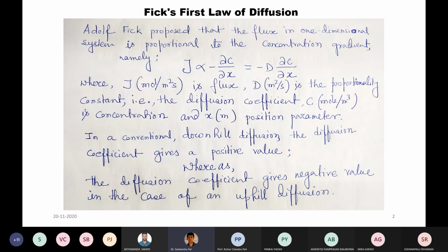And if you want to look at it more critically, it can be applied directly only if there is no change in concentration profile with respect to variation in time. That is almost impossible to find in most practical examples in the metallurgical industry sector, in metallurgical phenomena. So this is a real problem in applying Fick's first law to all kinds of metallurgical phenomena, because mainly things are unsteady, and the diffusion profile or concentration profile depends on time. That cannot be explained by Fick's first law of diffusion.